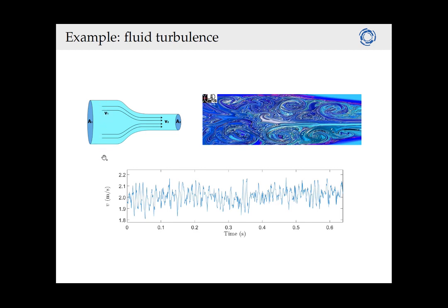points inside the cross-section, and if you do this with respect to time, you're going to see that on account of that turbulent flow, you're going to have fluctuation in the individual measurement points. If you calculate the average of that, that gives you an average velocity at various points along that cross-section, so at various measurement sites.